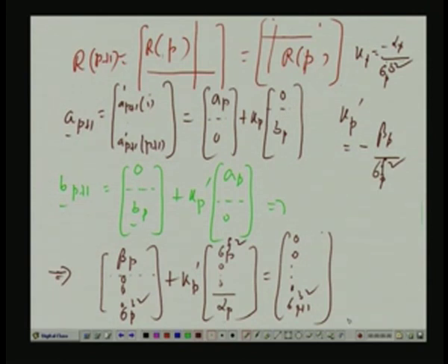In fact, there is no time to go into all those details, but K_p and K_p prime can be shown to be the same in this equation. In fact, one is the conjugate of the other, to be frank. K_p prime is the conjugate of K_p and vice versa. Sigma_p b square and sigma_p f square are the same, that comes from stationarity. These results I am not showing here. So, from the past solution you can find out the future solution. The only thing is how to start the recursion.